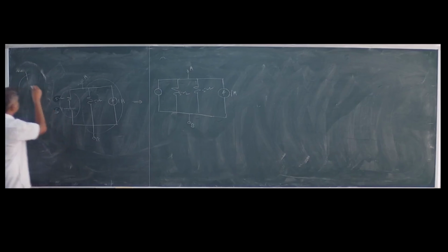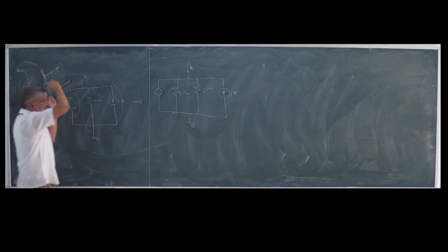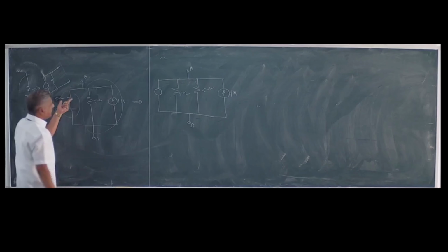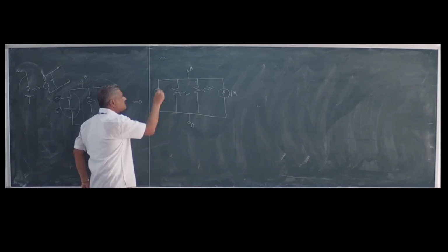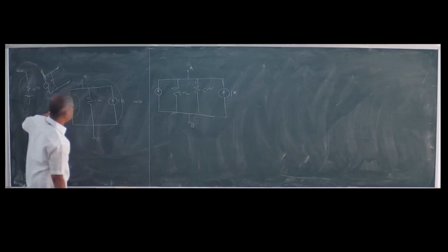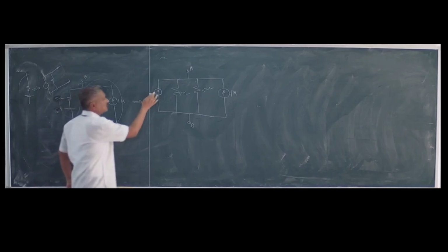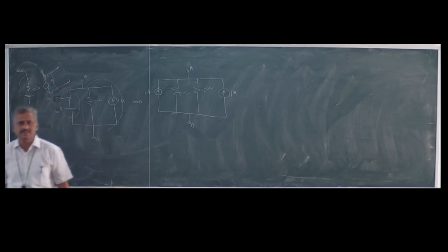Miss, here, how is the equivalent current source? This is the voltage source, and its equivalent current source will be something like this. Here is the equivalent current source, which is this, and I have replaced this circuit here. That's it. Here is the 5 ohm. I copied that as it is. And now the direction of this source will be upward, because the positive terminal is upward. And how much is the current? It is 1 ampere. Is it right? 1 ampere is the current.